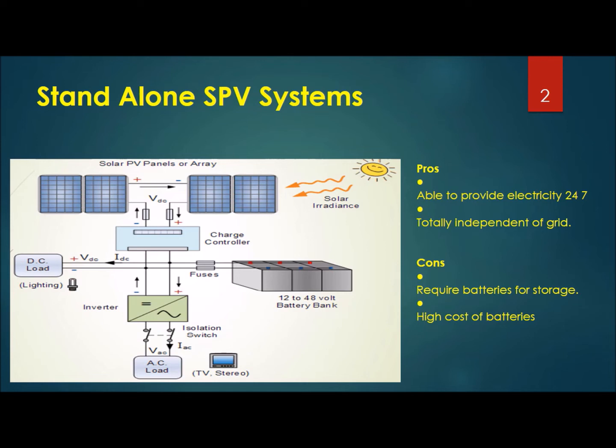As there is no grid in a stand-alone system, the output voltage has to be controlled in terms of amplitude and frequency. The stand-alone control is featured with an output voltage and frequency controller capable of handling variable loads.